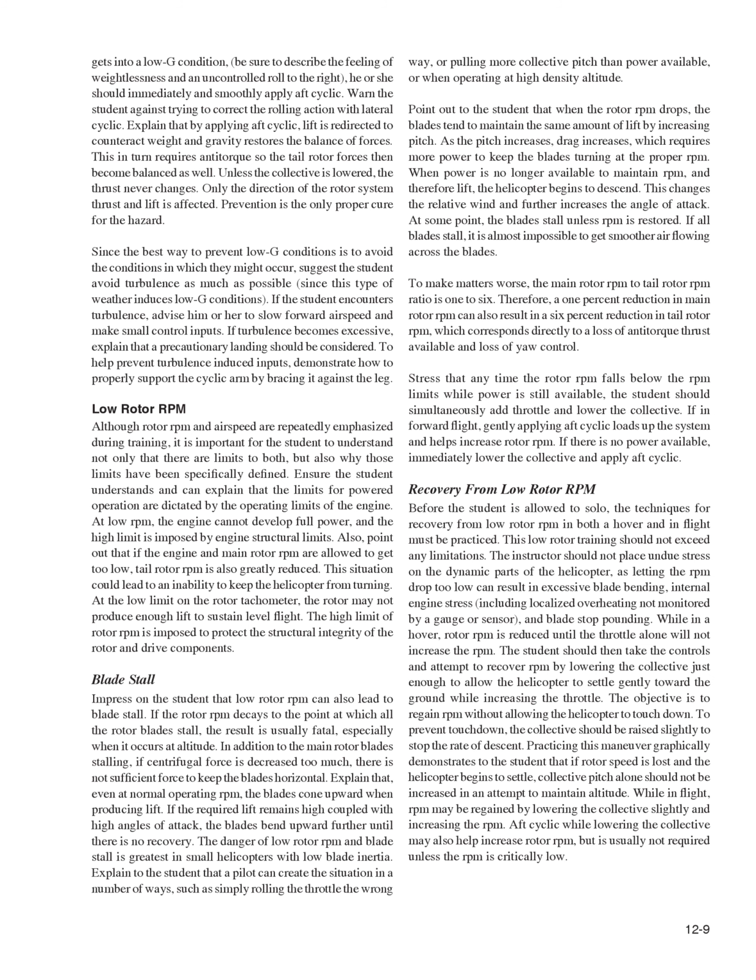Recovery from low rotor RPM before the student is allowed to solo. The techniques for recovery from low rotor RPM in both a hover and in flight must be practiced. This low rotor training should not exceed any limitations. The instructor should not place undue stress on the dynamic parts of the helicopter, as letting the RPM drop too low can result in excessive blade bending, internal engine stress, including localized overheating not monitored by a gauge or sensor, and blade stop pounding.